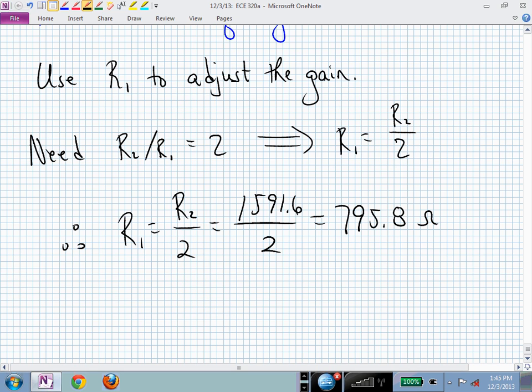So yes, it's a little bit more interesting, but you can still scale all of these parameters with the same scaling factors. You can do a magnitude scaling and a frequency scaling. It's just that the band pass region will scale to whatever it was percentage-wise in the original design. So if you're okay with that ratio of center frequency to band pass region, you're okay with these formulas. We'll pick up somewhere close to that on Thursday.